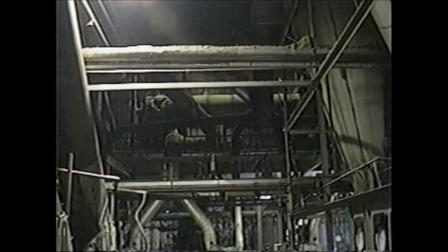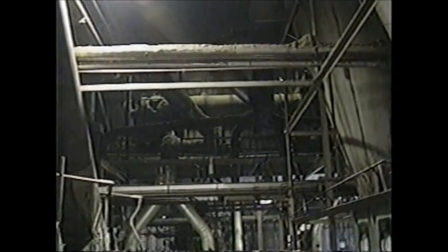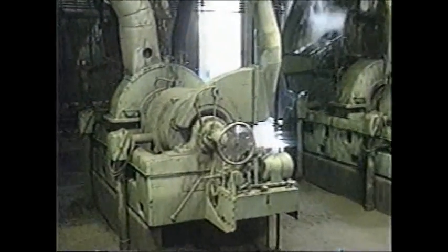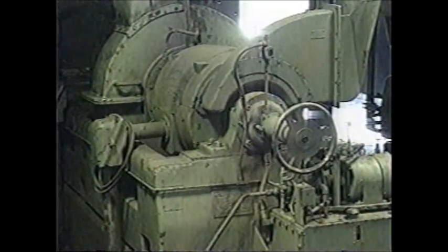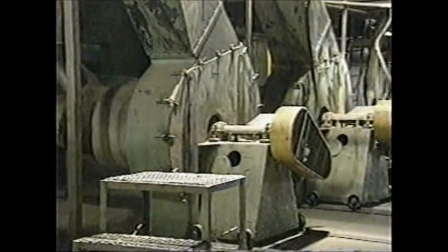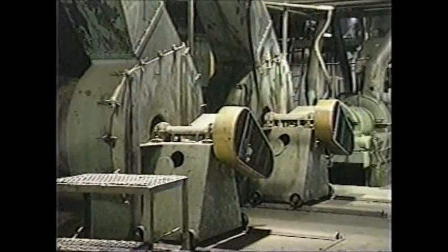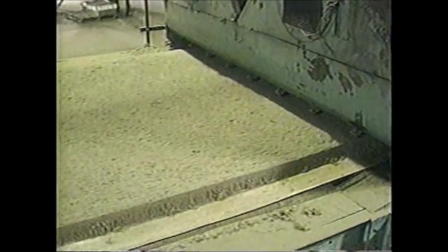Chips entering the plant are routed through a digester where chips are steamed for 5 to 7 minutes at 90 to 100 pounds pressure per square inch before passing through refiners for reduction to fiber and the injection of phenol formaldehyde resin. Fiber is then conveyed through a series of fans and collectors while drying and being delivered to mat forming machines.